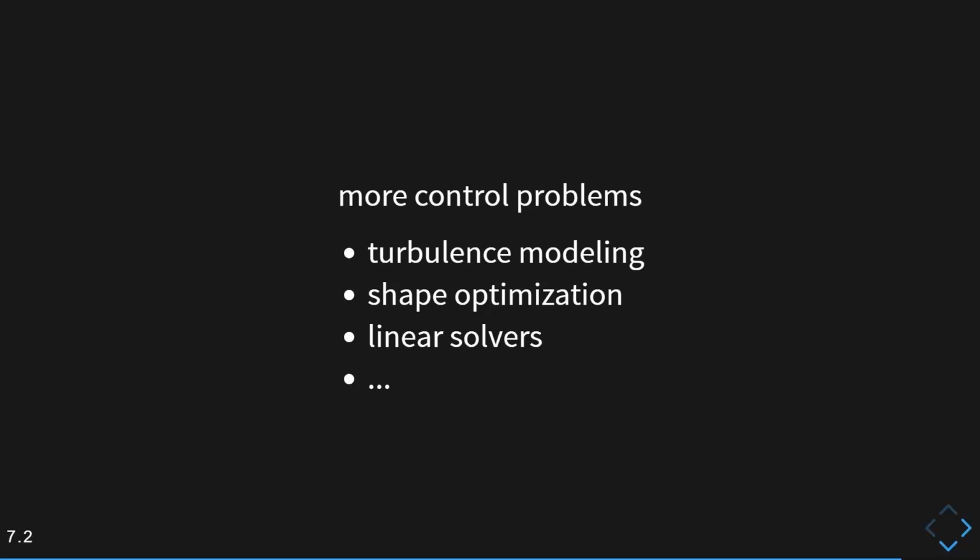You want to know, in order to match the average velocity profile that I got from my simulation, or from my experiment, for example, how my subgrid scale stresses would have to look to achieve this kind of average velocity profile. So it's basically a control problem in the sense that you would need to manipulate your subgrid scale stresses over time, such that averaged over time, you actually get the right target quantity, like your mean velocity. So just to give you one more idea.